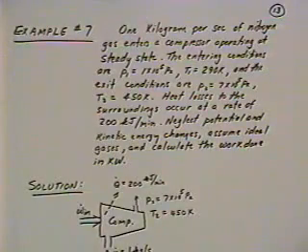The temperature is 290 degrees Kelvin, so this is again sort of an atmospheric condition where you've got nitrogen entering, and you're exiting at P2 of 7 times 10 to the 5th pascals, so you've got a compression ratio here of about 7 to 1 on the nitrogen. The leaving temperature is 450 degrees Kelvin, and although one of the assumptions normally made for compressors is that there are no heat losses, in this particular case we do have heat losses that occur at the rate of 200 kilojoules per minute to the surroundings.